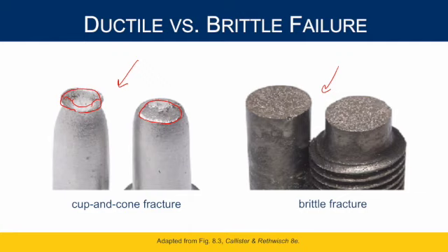So when you're pulling apart, the cross-sectional area starts to change, and then it starts to tear at the weakest point. It usually starts to tear from the inside first. You get these little bubbles where it tears away from the material. And then the edges are the last to go. That's the last part holding the two materials together. And then it tears at these 2 points. So this is a typical moderate ductile failure that you would see in metals.